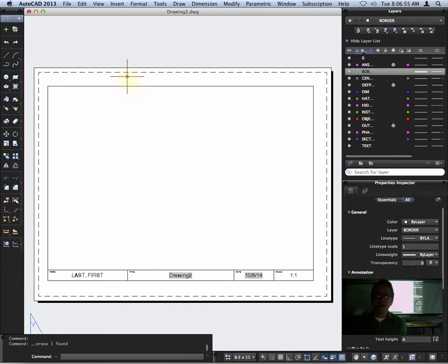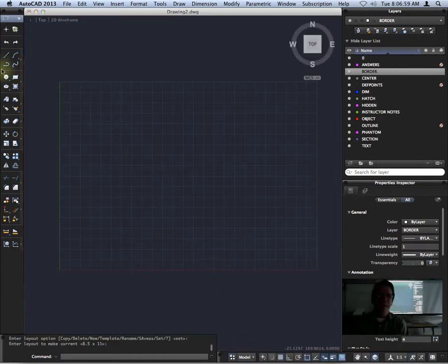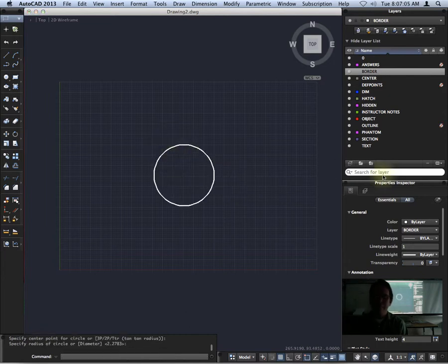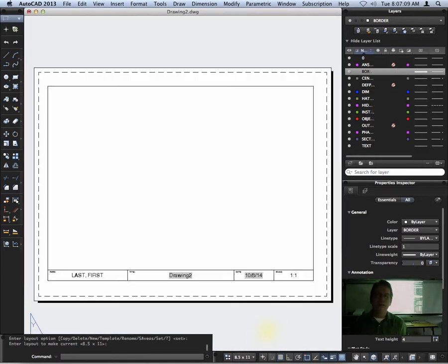So now I'm going to go back to my model space here, and I'm going to draw the top of my telephone pole again. And now I'm going to go back to my paper space because I'm now ready to print it. Where's my telephone pole? Well, remember how we deleted our viewport? We need to make our viewport again. So I'm going to go MView.